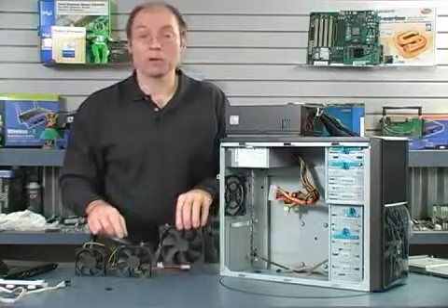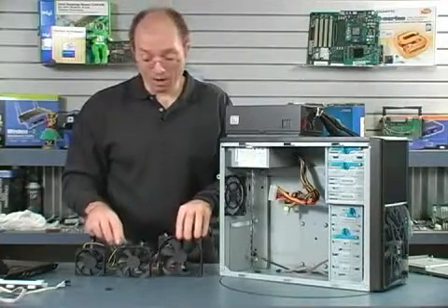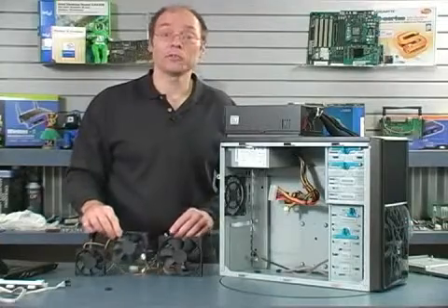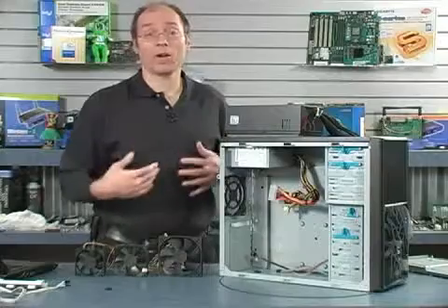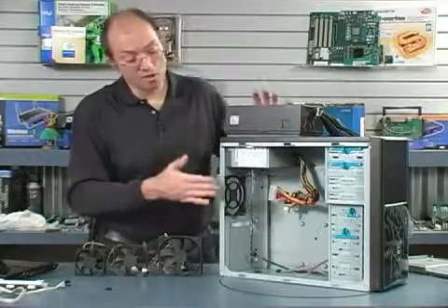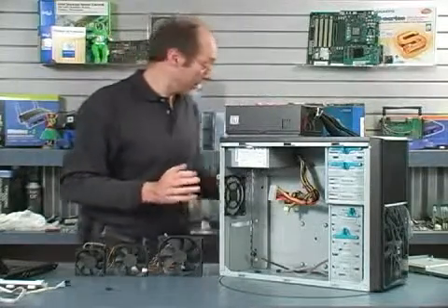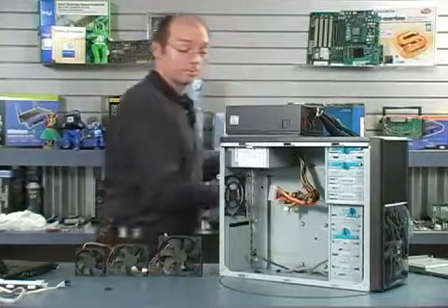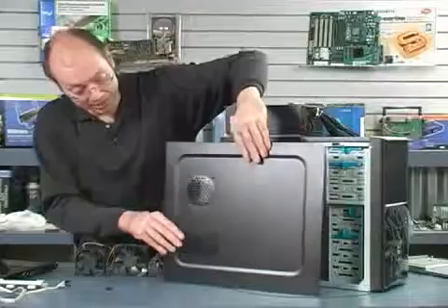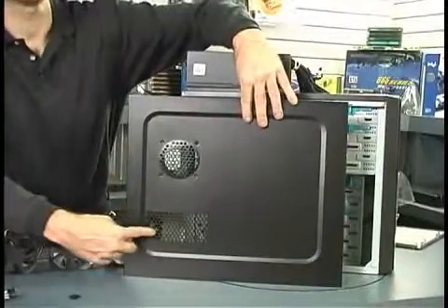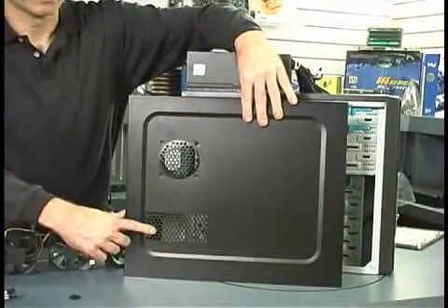So if I have a 120 millimeter fan on the back blowing air out, I generally like to have a 92 millimeter fan pulling air in on the front. Now, why do you want more air going out than in? Well, because there are other vents on a case. For example, if I show you the side panel for this case, you can see that it has several vents. There's a vent here. This is a vent for the video card.